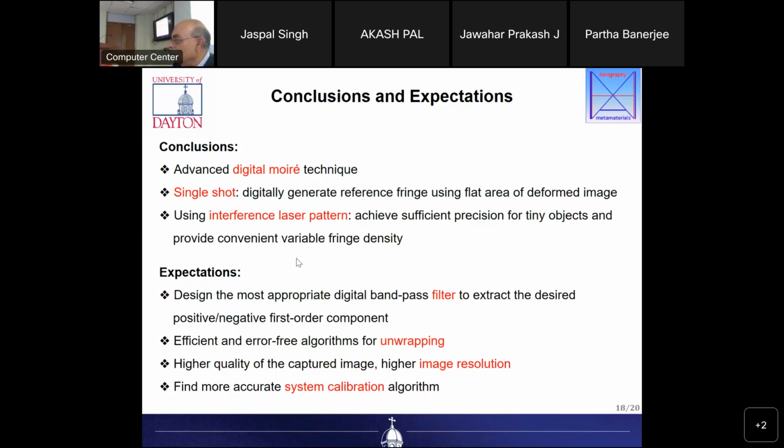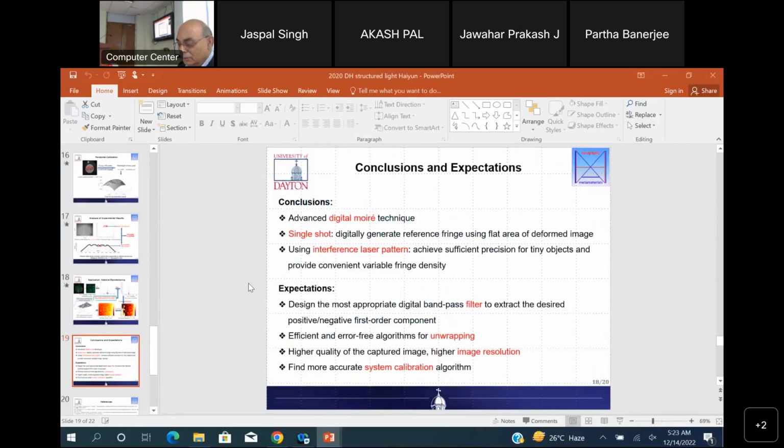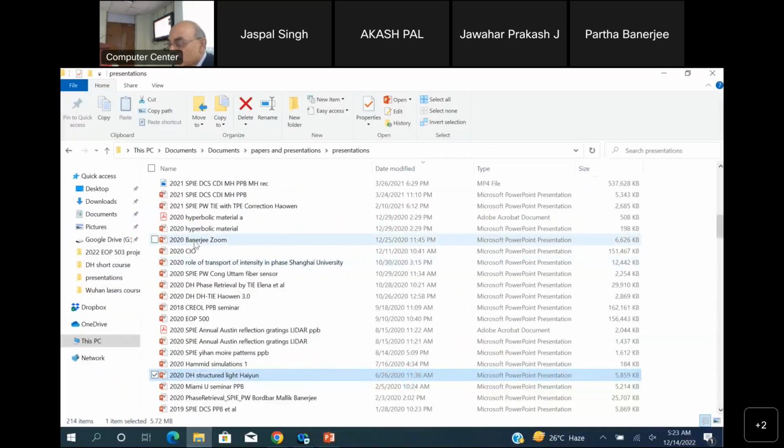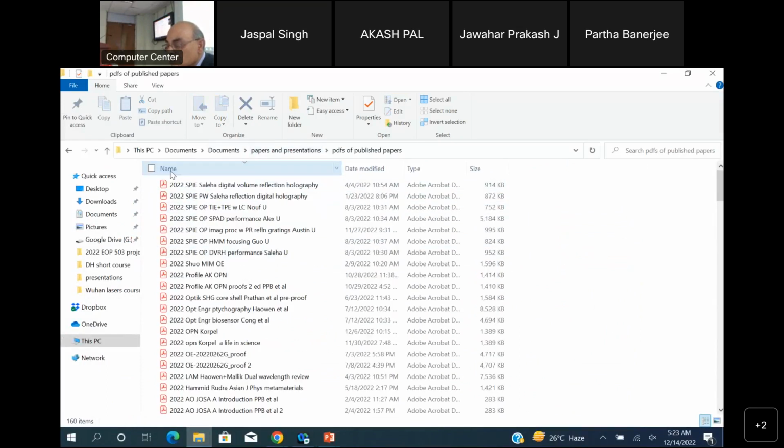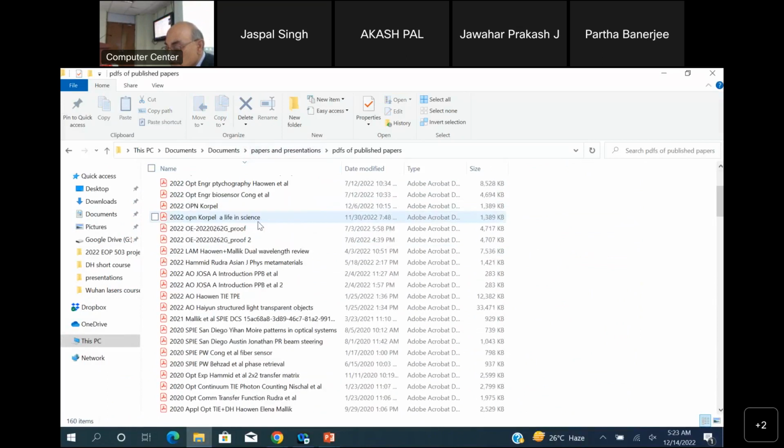So this was also applied to thick lenses to see how the quality of the thick lenses was. And there was, again, a very interesting calculation, because as it turned out, these Moire fringes, of course, will now look like a chirp pattern, because as the shape is changing, the curvature is changing, the distance between successive Moire patterns will become smaller and smaller and smaller. Does that make sense? I might have actually a copy of that reprint of the paper. If I do, I'll show it to you. And after that, we'll take a break.